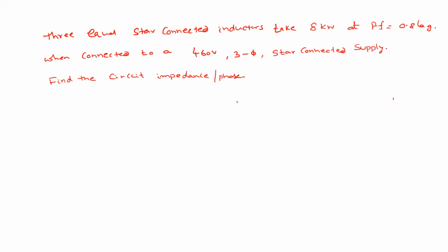So what is given here, right? Three-phase star connected inductors will take 8 kilowatts. The thing is that an inductor will not consume any energy. So these are practical inductors, so that means the inductors have some resistance also. And these are operating at 0.8 power factor lagging.